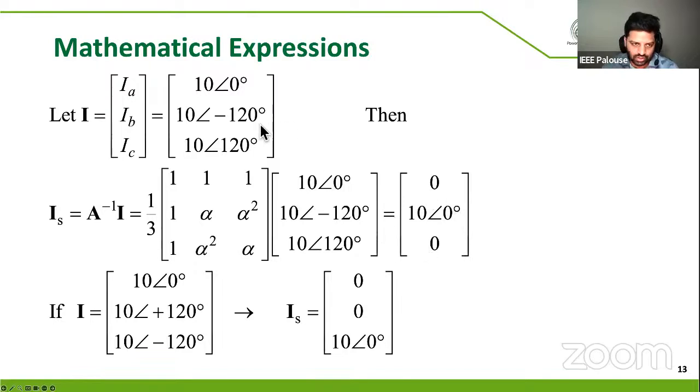If you observe, the example system that is shown is actually a balanced system. So if you take a balanced system and apply the transformation matrix, all you're going to get is only the positive sequence component. As I explained in the beginning of this slide, you'll only get the negative sequence and zero sequence components if you have an unbalance in the system.